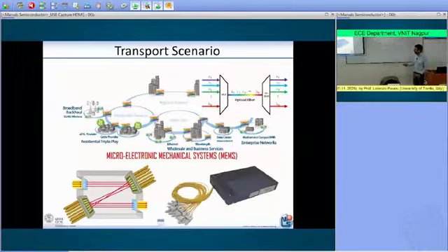In one of these MEMS-based systems where you have many fibers, the key component is the rerouting of the optical signal. You have a mirror which is actuated by MEMS. The MEMS are moving the face of the mirror, and this movement can be quite fast because the mirrors are quite small. It can happen at a gigahertz rate. However, you need to align very carefully.